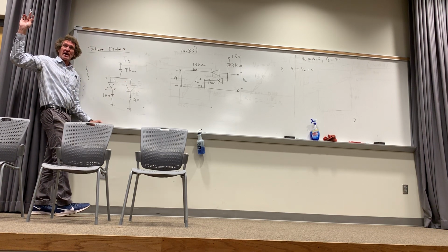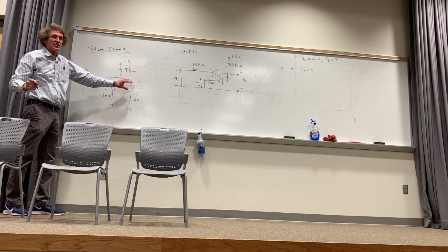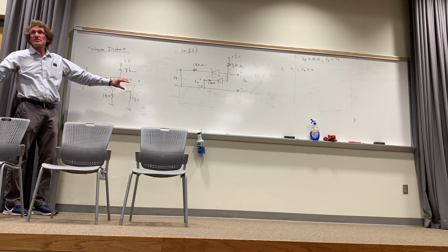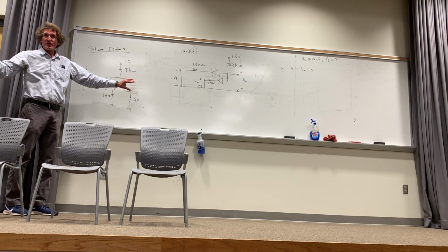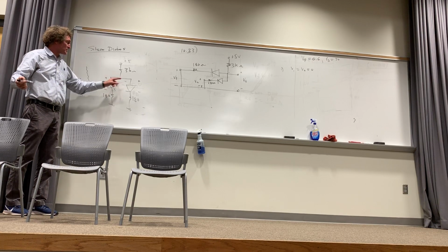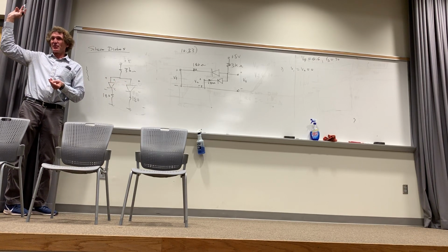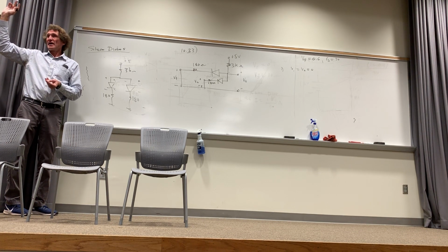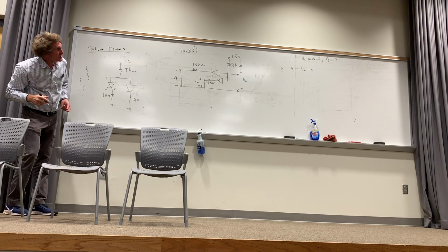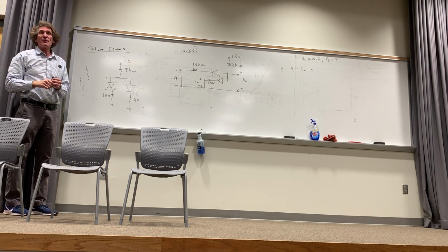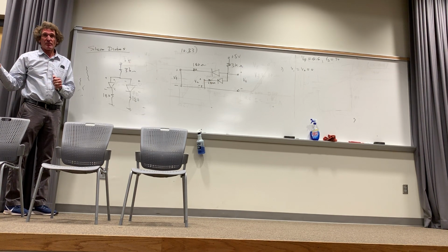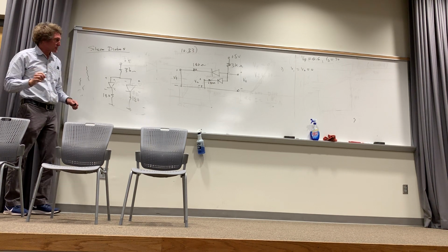I'm trying to do this rationally with everybody. If you just remove the diodes, what I'm going to see is whether there is enough voltage there to turn them on, for starters. If you take both of these diodes off, you get 5 volts here and 5 volts here. Do you all agree? Give me a show of hands if you do. Yeah, there's going to be more than 0.6 volts or whatever that was, right? 0.6 volts. So now if they're both on, and you all agree they're on, I'm going to go through the permutation so you see this.